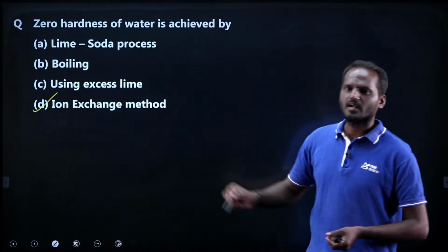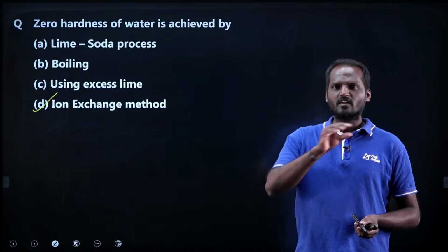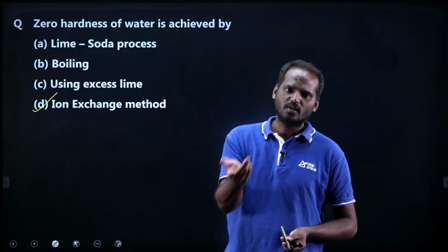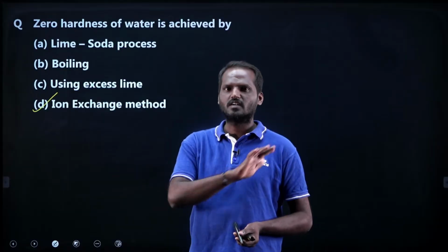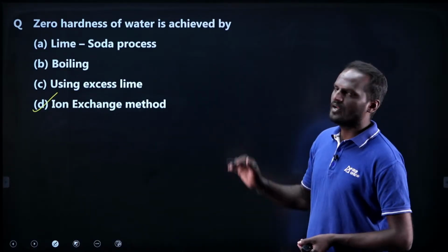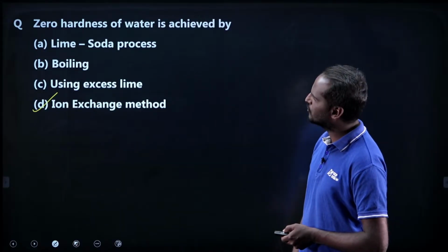This is what? Complete removal of hardness. You may not find even a single milligram per liter of hardness, no hardness at all. That is achieved by the ion exchange or zeolite method. Okay, this is about zero hardness.